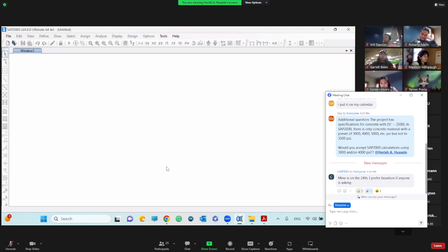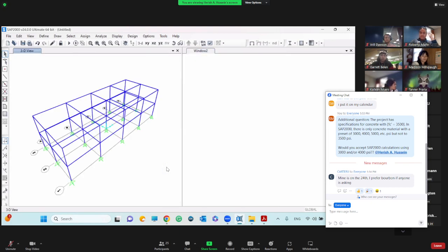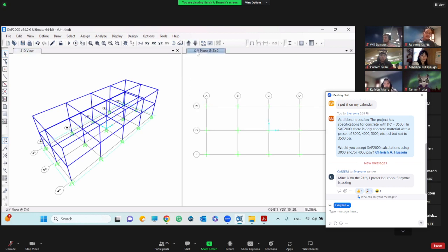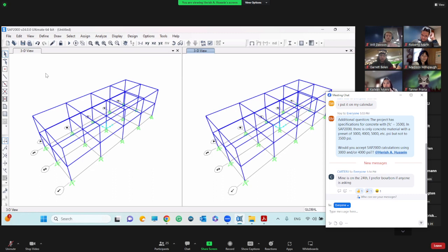And then we click on it, it generates a 3D model for us. It opens 2 windows. Usually I keep the right one in 3D. You click on this 3D. See, you click on the window here. When it's highlighted blue, it's active. You click on the 3D. It generates your 3D. And I come back on this window. I work on this window. I make it kind of bigger, drag it to the side.